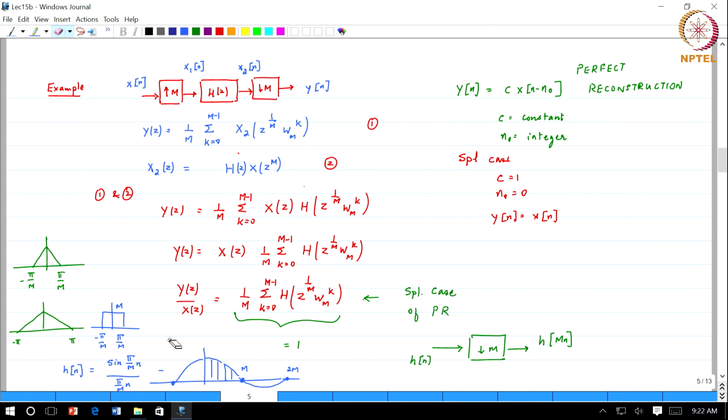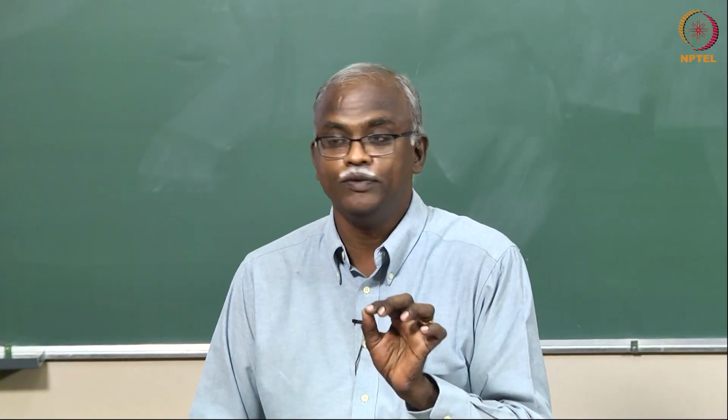That is where you have the 0 crossing. Now, think of this as some impulse response h of n, and you pass it through a downsampling by a factor of m. What will you get? The 0th polyphase component, which will be, this sample will be non-zero, all of the multiples of m will be 0. Okay. So, it is perfectly consistent with that.